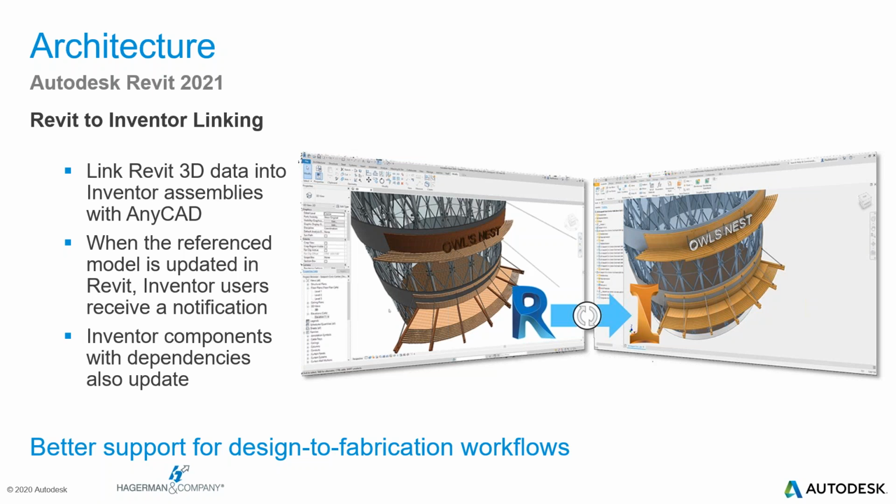Okay, so let's take a look at some of the new goodies included for the structural discipline in Revit 2021. Reinforcing bar assemblies, known as standees, are normally required for the support of top mats of reinforcing bars in thick concrete members, such as footings and slabs. These standees have a 3D rebar shape.